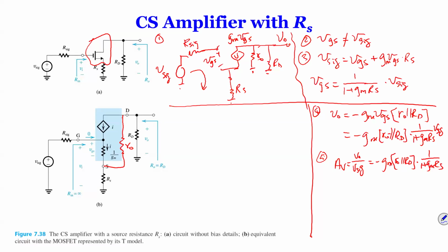Yes, it does. Okay. So the other thing to remember is no current into the gate. Okay. So that's something you've got to remember. Now this connection, even though there's no current, we still connect it because connecting means the potential over here and over here are the same. If you open this one, it becomes misleading because we don't know whether the voltage over here and over here are the same. So you can do the same procedure, and then you can find the actual gain will be similar. You can do it, but today we're going to skip that one.